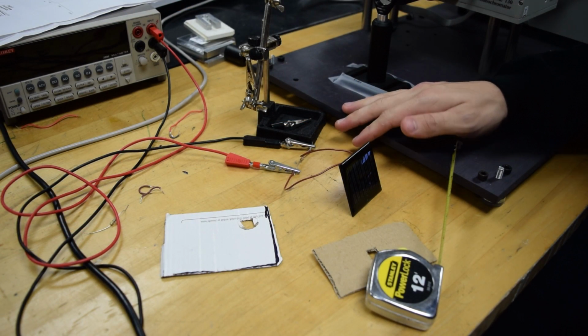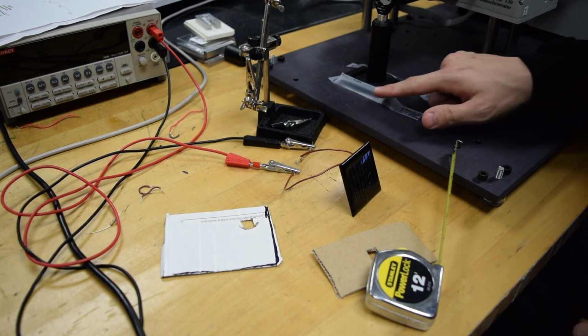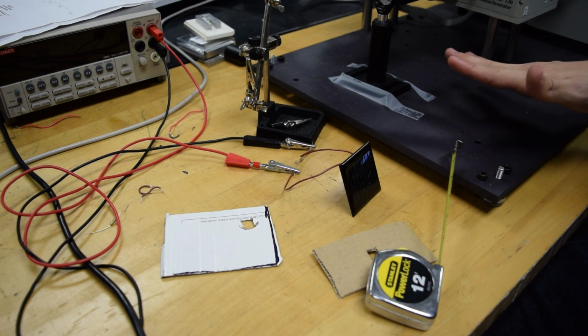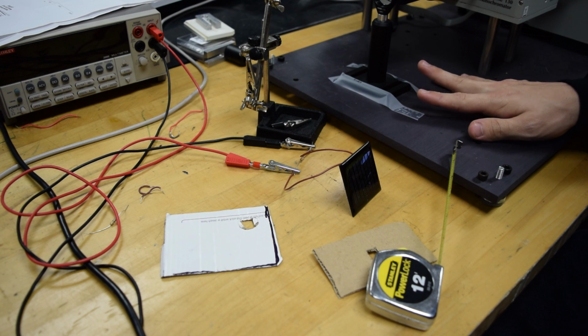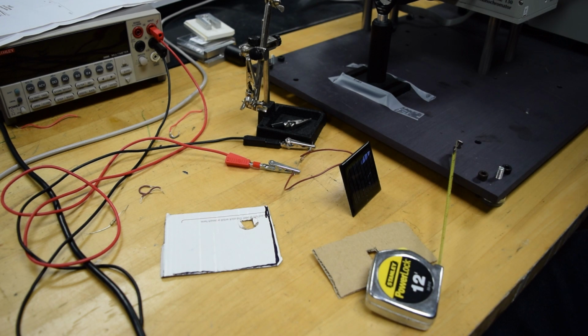We're going to have to use some optical mounting to kind of, not necessarily jerry-rig, but get our cell in place to where we want it. I've taped off our lens over here so it's not moving anywhere, and it's in a fixed spot. That's an arbitrary distance. You can do that however you please, as long as the lens isn't moving between the power meter and the measurement for the silicon cell itself.